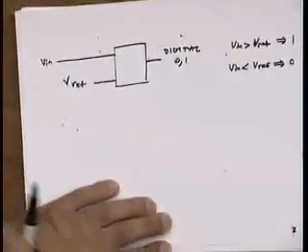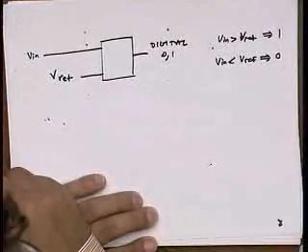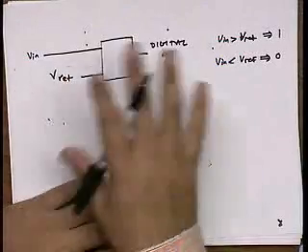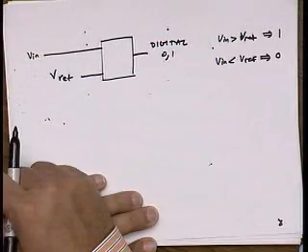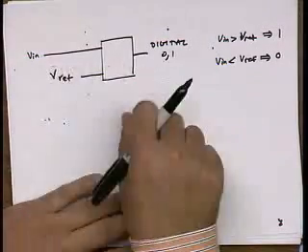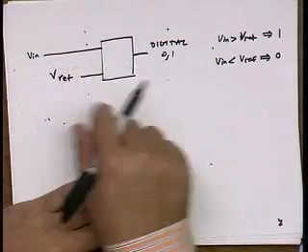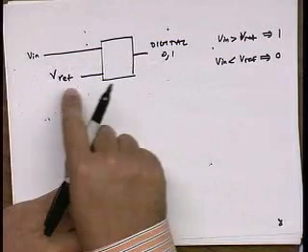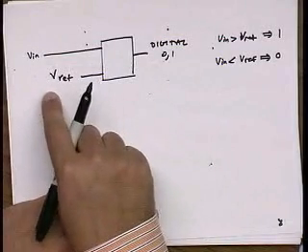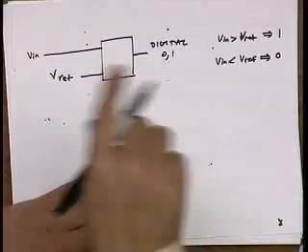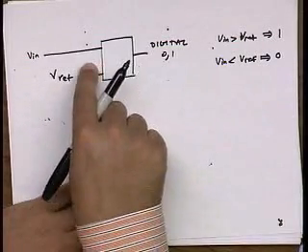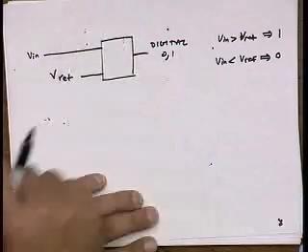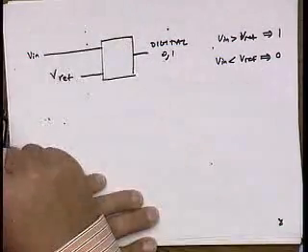And this is a very useful building block. At the very simple stage, right, it can detect, let's say, an AM signal, right? If this is the envelope of an AM signal, then if it's bigger than 0, let's say 0 or some reference, this reference may be something that a feedback circuit has determined, the average reference of the signal, average power of the signal. So if it's bigger than some threshold, it's a 1, otherwise it's a 0.